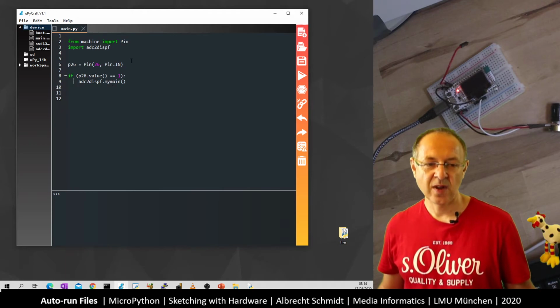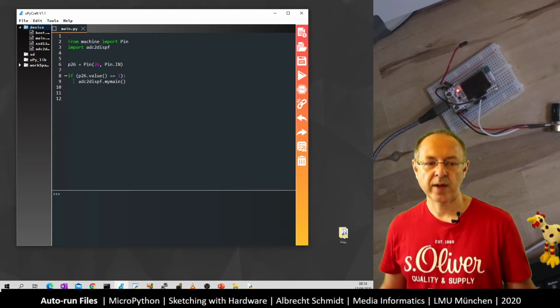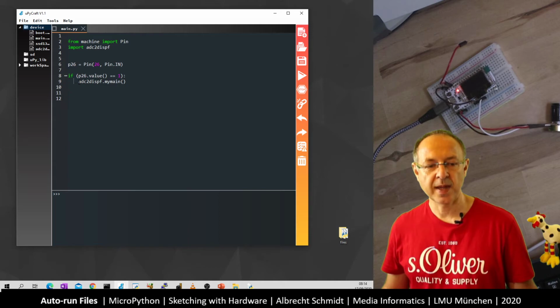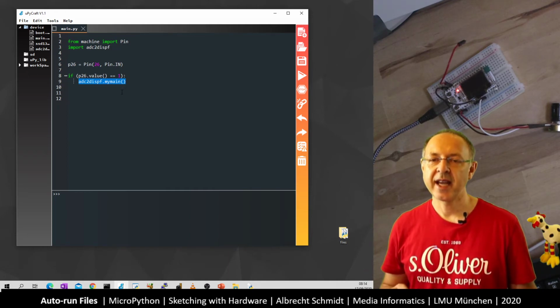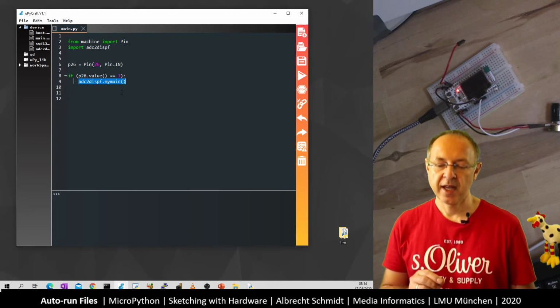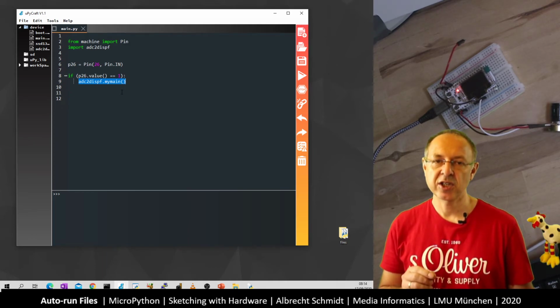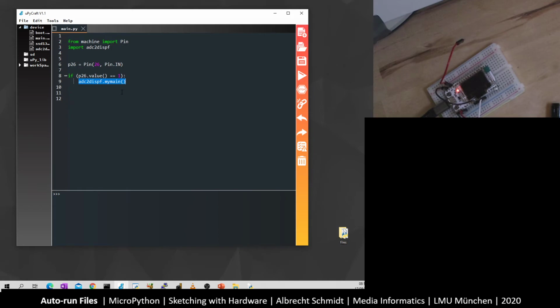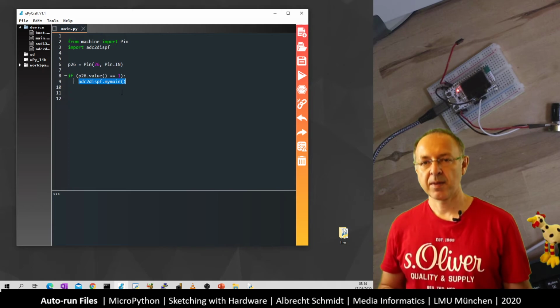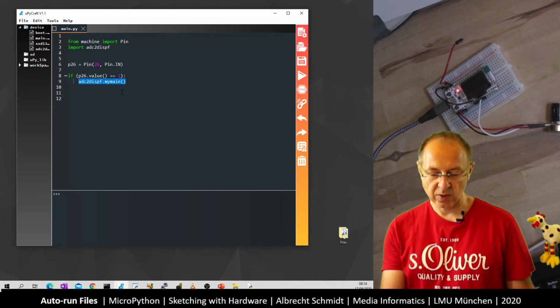And so this is quite useful, and I would recommend to use this main file where you basically just exchange the software you write, what you wrote, and what you call, but that you dedicate one pin for whether you want to start it or you don't want to start it. And you can use the switch that's provided in the box to make a boot selector, whether you want to boot into the development mode or you want to boot into the real thing. And I just lost the camera here. It's coming back. So let's quickly show you the switch.